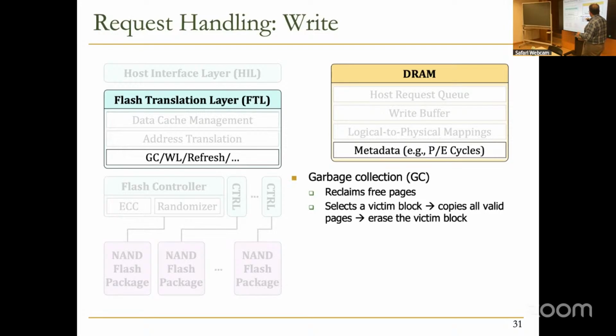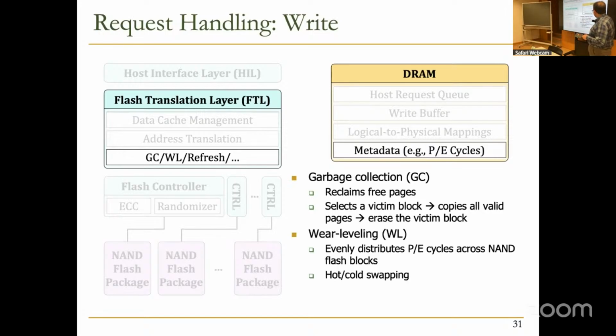So garbage collection, which we're going to see today, is to reclaim free pages. Because when you write out of place, at some point you are running out of free pages, right? So then there should be a process, which we call garbage collection, that tries to reclaim free pages by erasing some of the old and invalid pages. So we're going to learn about garbage collection later. I don't want to go into a lot of detail now.